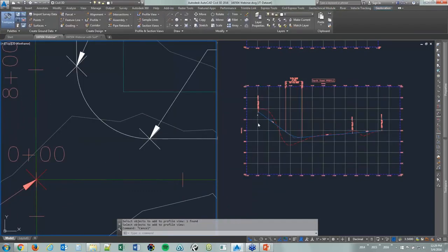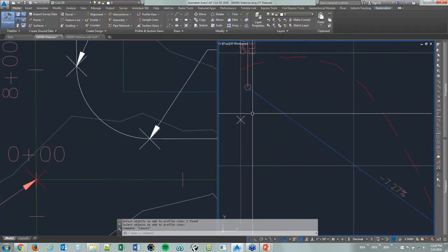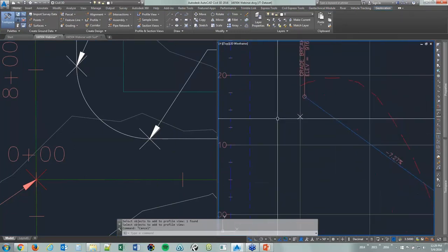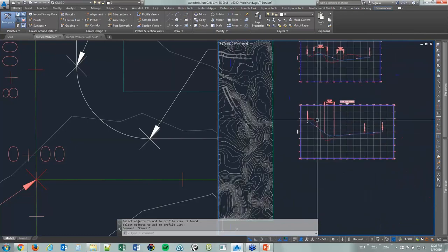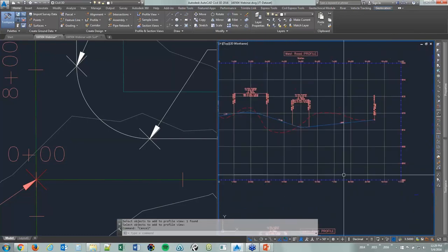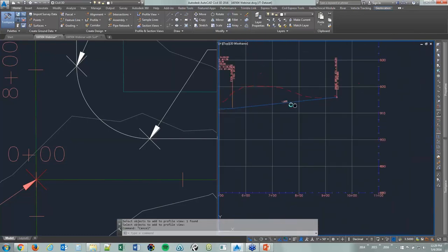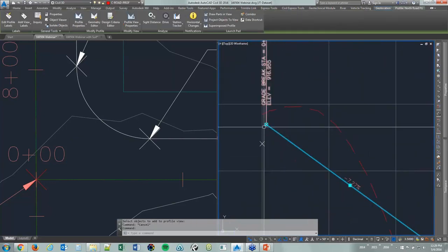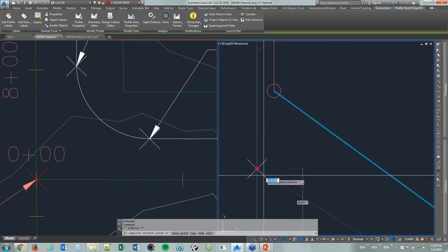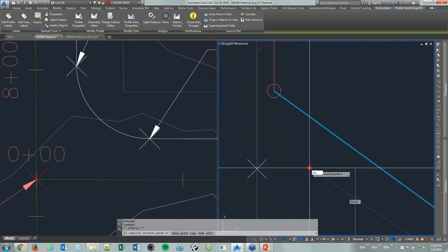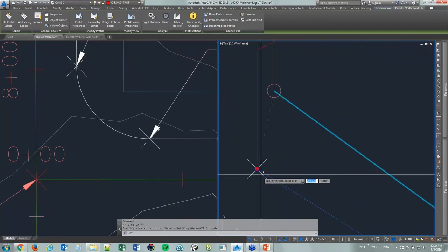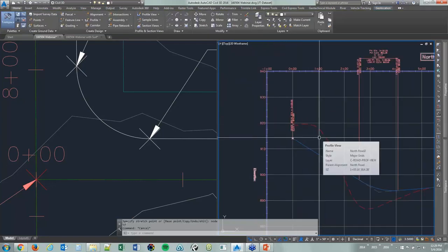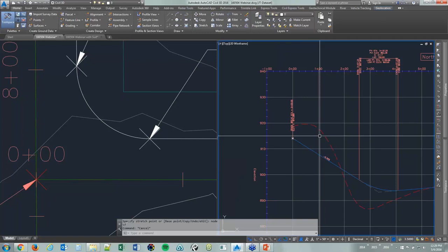You can see that right at that spot, and that is somewhere between 910 and 920, that 914 elevation. Look in here, just before 8, that does look like it would match correctly. So now this is a node snap, and I can snap this profile, and that's node, right to it. So, just another neat trick.